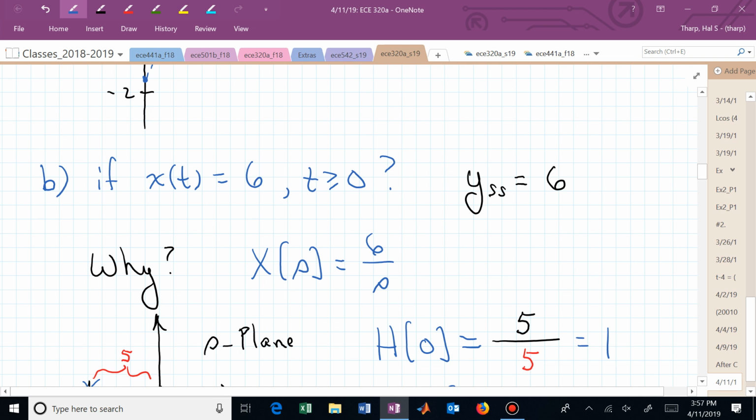So now you have this exponential behavior that you're used to seeing when you charge up a capacitor. That's what's happening when you're low-pass filtering a constant. And how quickly does it take to charge? 5 tau, which is 5 times 1/5, in this case, 1 second.